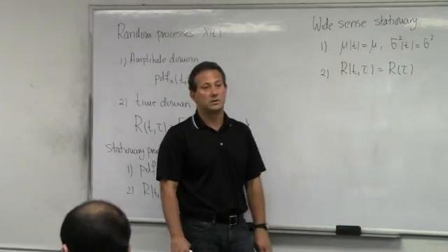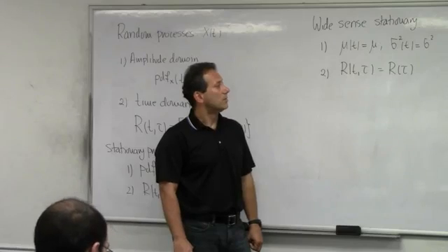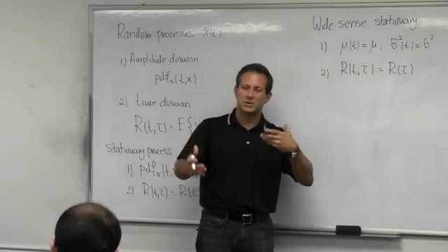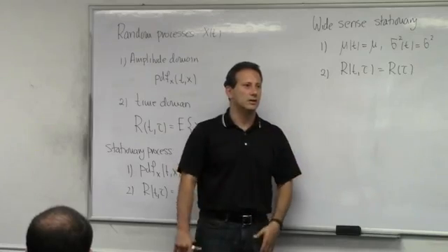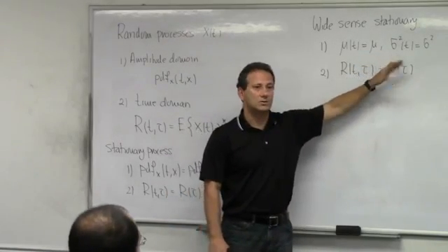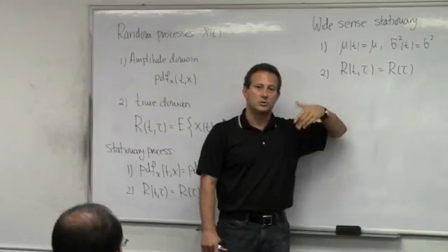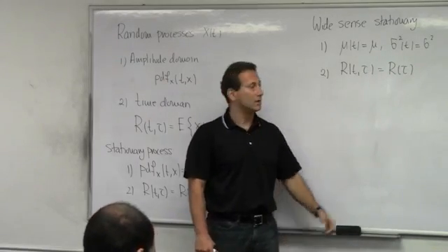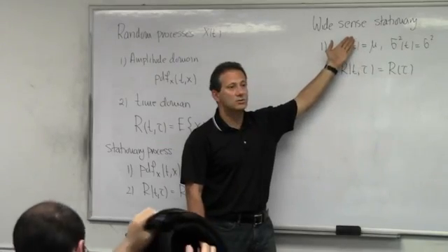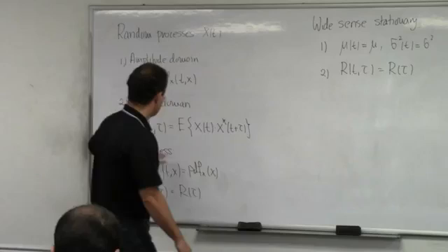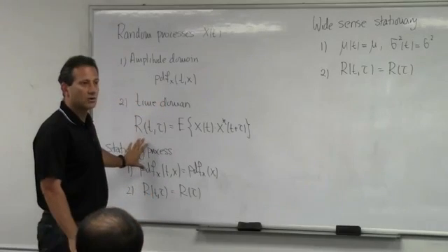There are algorithms where this is also concerned, but in most of the algorithms that we deal with, especially when you talk about signal to noise ratios and those kind of things, then you really just talk about the powers, the ratios of the powers, and it's important to say powers do not change over time. Powers are stationary, and this is, as I said, weaker condition that's satisfied obviously more times than this stronger condition here.